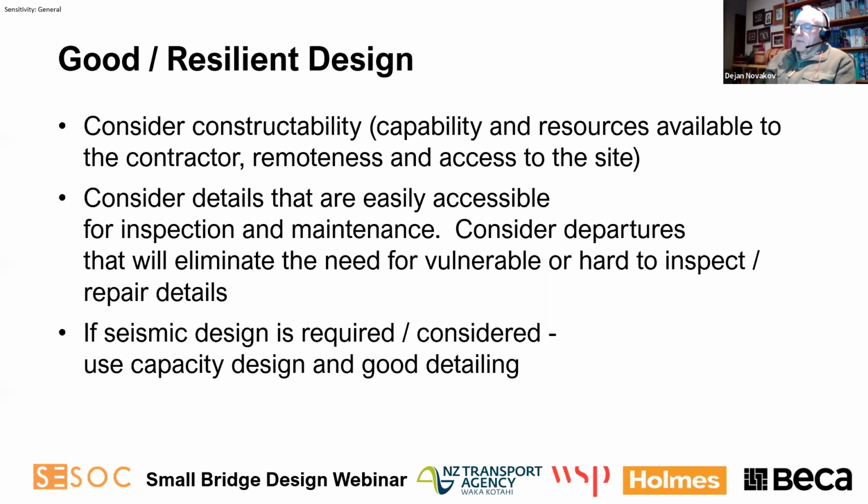If you're, for example, using timber, pressure treated timber next to the concrete, separate them to make the life longer. Consider departures that eliminate the need for vulnerable, hard to inspect repair details. For example, whether you need linkage bars.